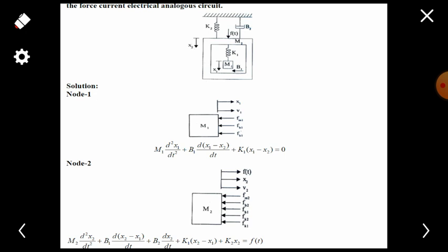First we are going to write the free body diagram. Using that free body diagram, we are going to construct the differential equation. After finding the differential equation, we are going to convert the value in terms of displacement to velocity. After that, we are going to change the mechanical elements to electrical elements, by considering the tabular column we have discussed before this.